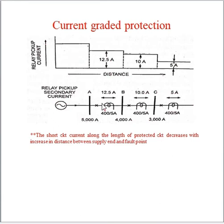If the fault is here, the fault current should be more than 12.5 ampere, then that relay will operate. And this is the relay pickup secondary current. Here only is the sensing point.